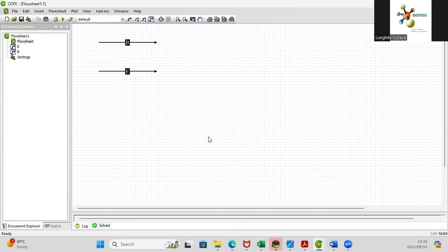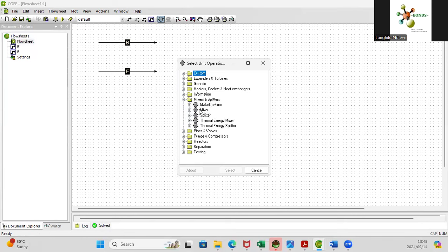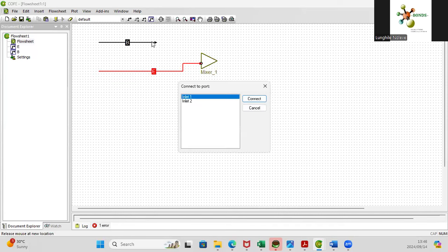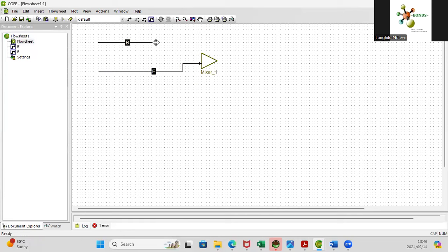So we've got two options. We can do that individually, or we can combine the streams, right? And then after combining the streams, we can then heat it up or compress it and do all of that. Now, if you check, your ethylene is in vapor and your benzene is in liquid. So the first thing I would do is combine them and see what phase comes out after that. So again, my target is to do the reaction in liquid phase. So let's see what happens when I mix them.